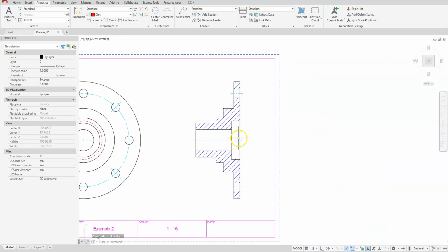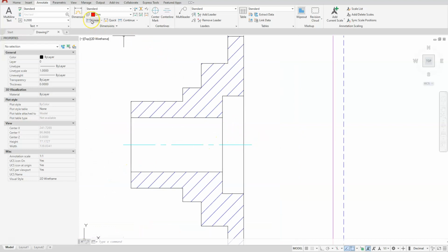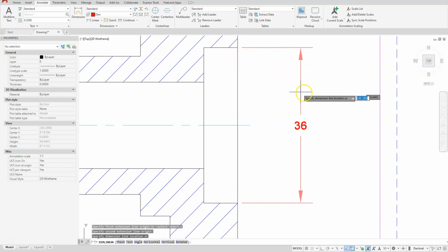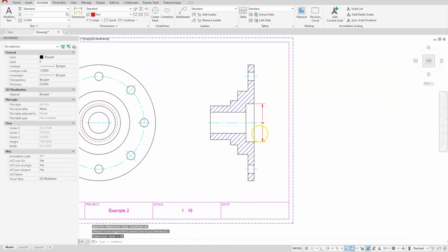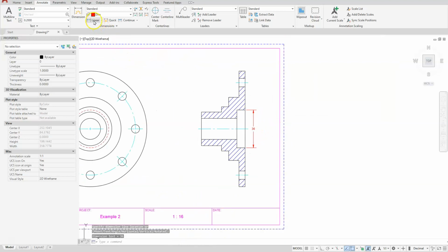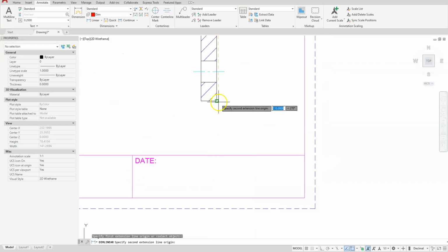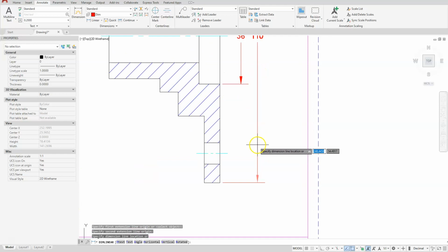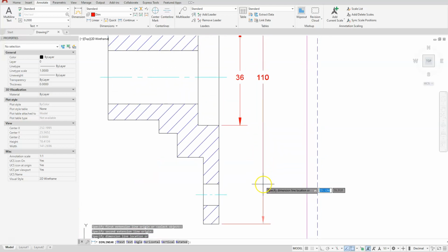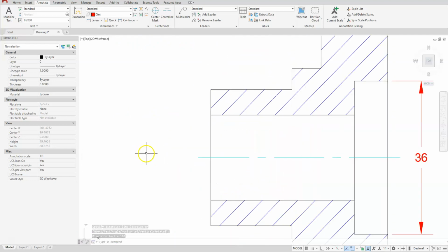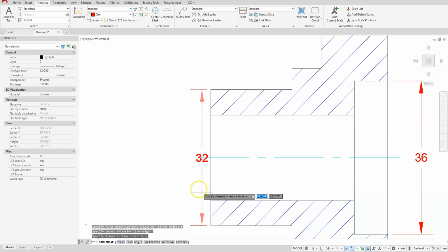Let's start putting our dimensions on the back side here. So I'll start with a linear dimension and put it at this endpoint and at that endpoint. Drag away from it and place my dimension. Do the same here at the top, so I'll select that endpoint down to that endpoint. I could have used the alternative method by selecting enter. I'm just going to drag this away at a comfortable distance, and that looks fine to me. Do one more dimension here in the front, that endpoint to that endpoint, and place it here.